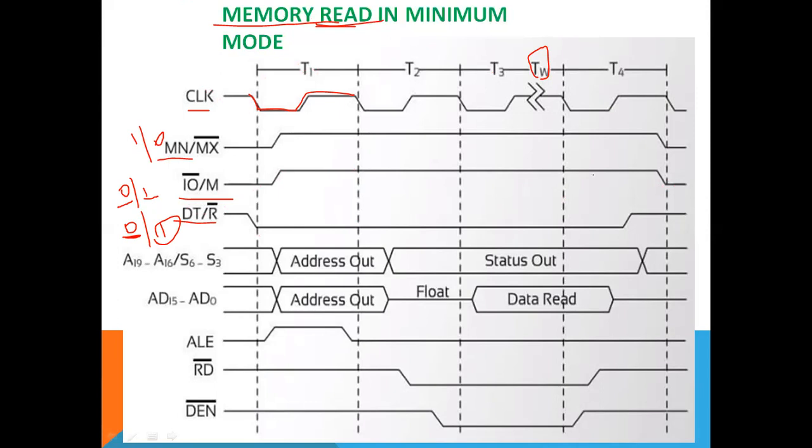So here, down states. So here address and selection line. First, the T1 state can be used to find out the address. Then we have to use the selection states. Next, address and data bus are multiplexed together. First, in the T1 state, find out the address. After that, we have to find out the data.